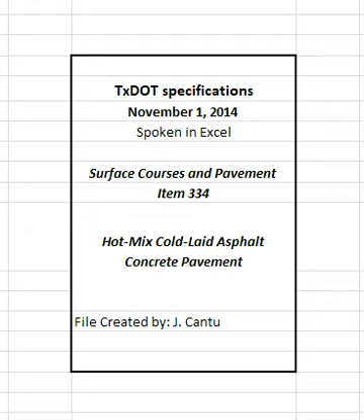4.2.4 Mixing and discharge of materials. Produce the mixture at a discharge temperature between 145 degrees Fahrenheit and 275 degrees Fahrenheit, as directed. Do not allow the temperature to vary from the selected temperature by more than 25 degrees Fahrenheit. The department will not pay for or allow placement of any mixture produced above 300 degrees Fahrenheit.